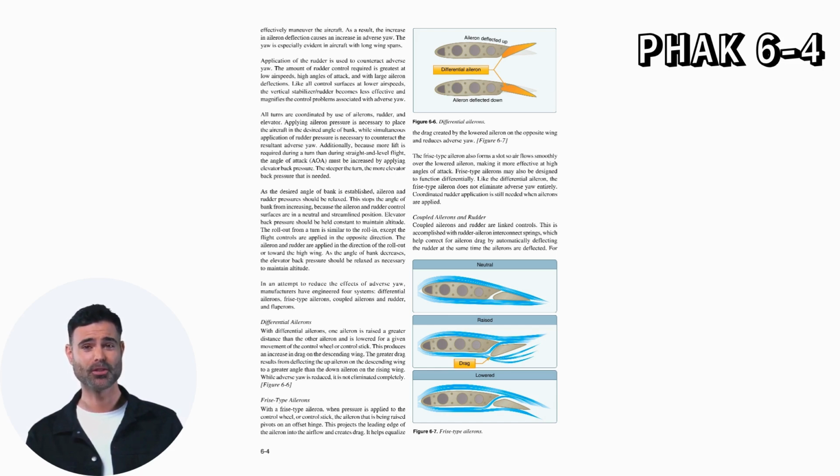This produces an increase in drag on the descending wing. The greater drag results from deflecting the up aileron on the descending wing to a greater angle than the down aileron on the rising wing. While adverse yaw is reduced, it is not eliminated completely.